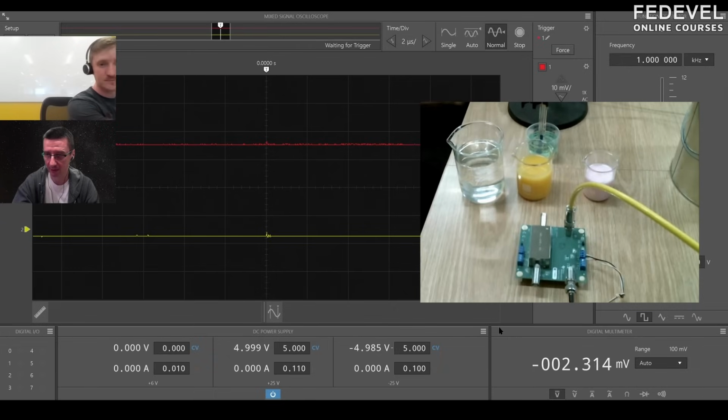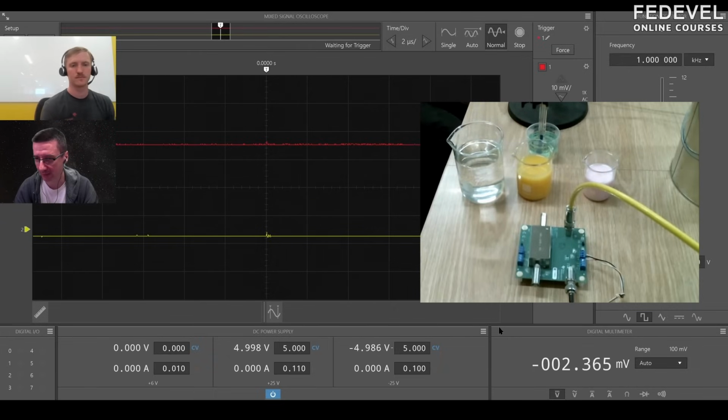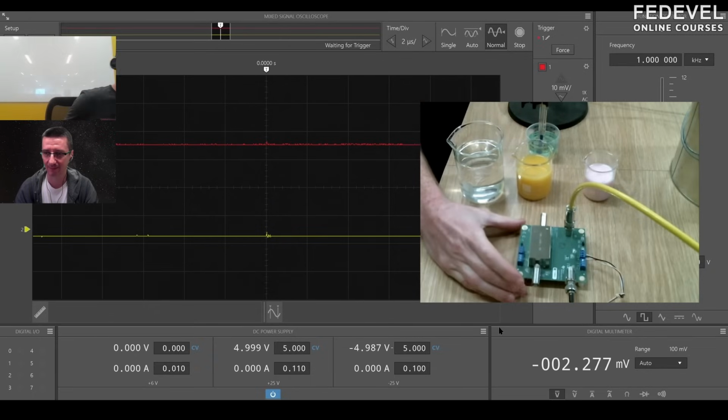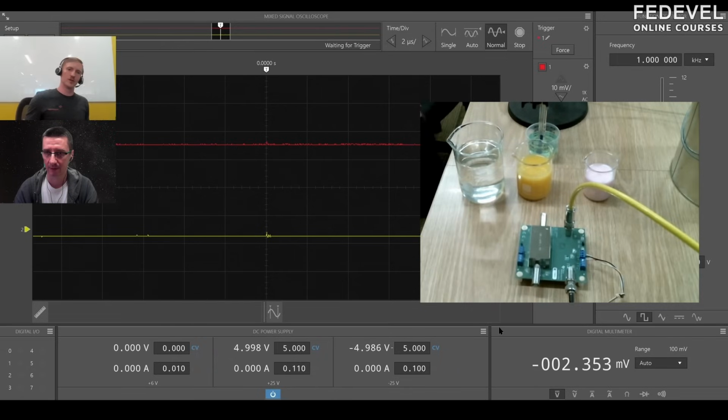And now you are using the good one or the bad one, the amplifier? Oh, so this one, we just have our OPA928 EVM. This is the only one we have set up. The other, that schematic was just an example of showing what you can expect to see if you actually set it up. But I actually don't want to pull too much current out of this probe because they can be very sensitive. And if you pull too much current out of them, you can even damage them. So I haven't hurt one of these probes yet. In the interest of making sure that's the case, we're just going to show the optimal solution here.